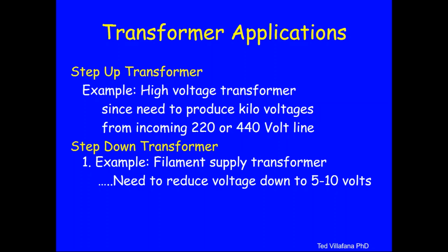We're very familiar with those types of transformers because when you charge your telephone or your computer, you're taking 110 volts from the line, you're passing it through the quote-unquote adapter charger plug, and that adapter is really a little step-down transformer to give you the required voltages. In an X-ray system, the filament supply will call for a lower voltage. Filaments only work at 5 to 10 volts. So again, you need a step-down transformer.